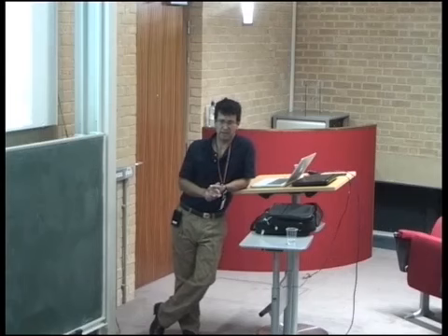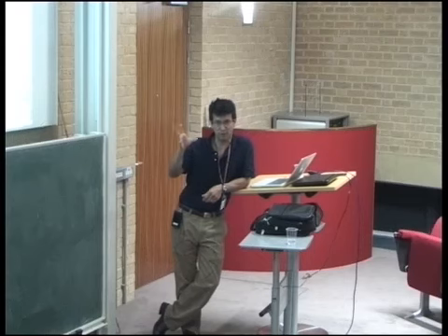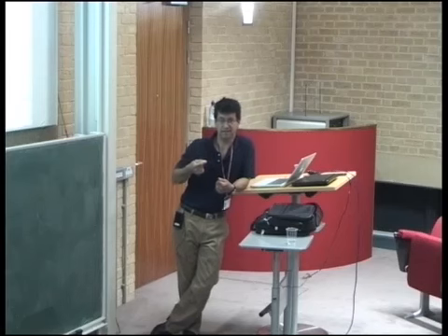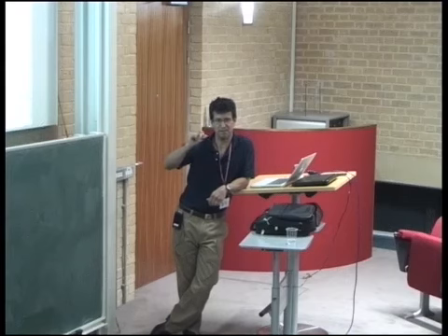If you only use multi-rate in that setting right now, the way multi-rate extrapolation methods have been used in the past is really not for AMR. It's basically for solving ODEs, right? And the idea is that depending on what is happening physically in a certain part of the domain is when these different numbers of multi-steps kick in, right? But if you turn that off and you say, I only want to do extrapolation, in other words, I want to let the number of multi-steps be commensurate with the size of your cell, or inversely proportional, then I see that.